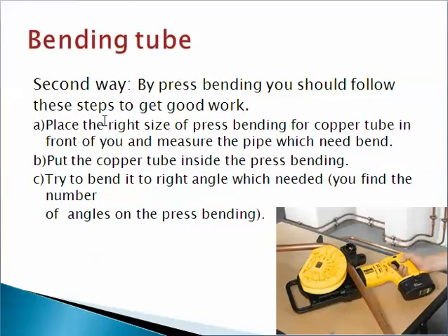Now I will talk about the second way. It is about press bending. You should follow these steps to get good results. A. Place the right size of press bender for the copper tube in front of you and measure the pipe which you need to bend. B. Put the copper tube inside the press bender.